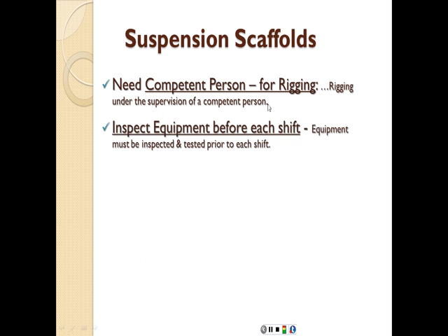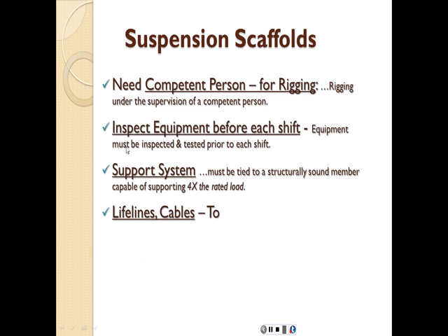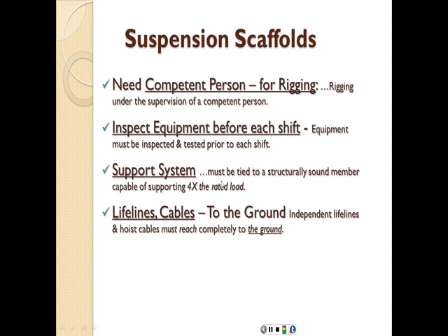You need a competent person for rigging. You need to inspect the equipment before each shift because conditions might change. It must be tied to a structurally sound member capable of supporting 4 times the rated load. So the ropes 6 times, the support system 4 times.